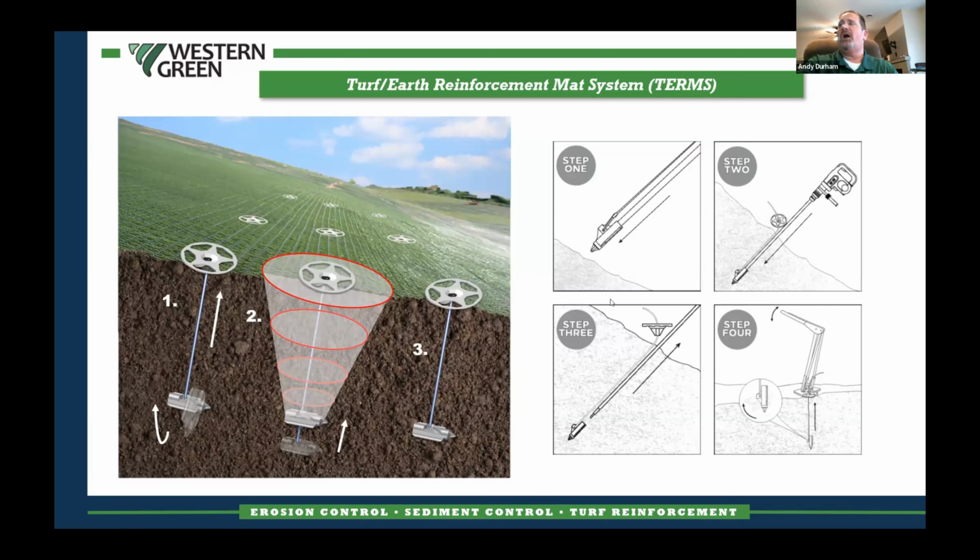cable tendon. Once the drive steel is in the ground, we pull it out, and then we tension the cable on the earth anchor. And by tensioning that cable, it'll actually turn the anchor foot in the grade so that it becomes parallel with the surface of the slope. And once you do that, you're radiating an entire cone of soil resistance that's deep seated into the ground below, where you might have the veneered high performance turf reinforcement mat on the top.